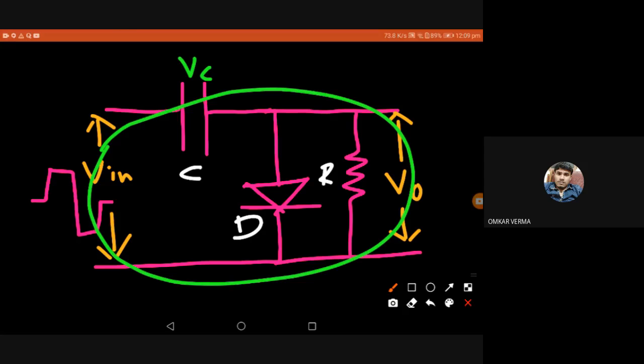Okay, so that is a non-ideal thing. You should understand that the capacitor does have a discharge option, but we are not allowing the capacitor to discharge. For example, there's a time constant like 5 time constants, 3 time constants. What time constant? Tau, the time constant RC, right? There's a time constant RC which decides the time required for the capacitor to charge and discharge to a particular level, maybe 63%, 90%, etc. So if we keep it larger, the capacitor will retain the voltage, so that we'll get a perfect output square wave, right?